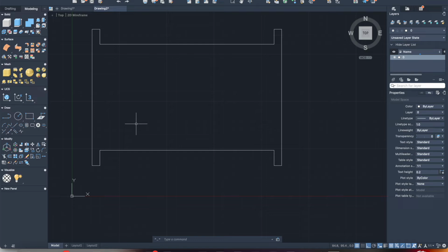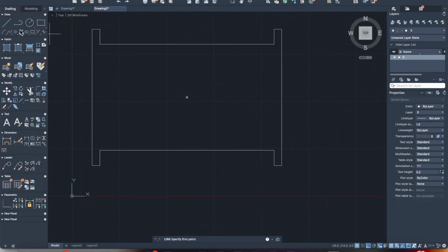Okay, so now we have a shell. It's actually going to be hollow on the inside. So we need to define the width of these wood segments so that we can see that it's hollow on the inside. In this case, probably the best bet is just to come down here, 10, come across 230, and then up 10.